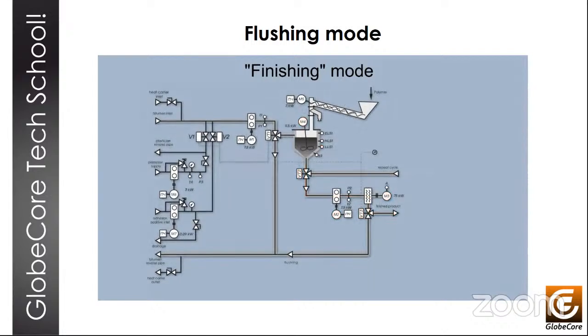And after stopping of the mill, the VT1 valve switches to the position of feeding bitumen to the mixer. The M1 pump is turned on in reverse, and the remaining bitumen is pumped out of the pipes for 20 seconds. And this now concludes that process, and the plant can be turned off or a new operating mode selected. Next slide, please.